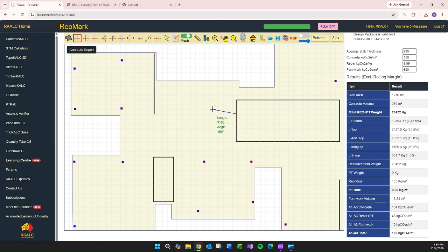Let's say I'm gonna draw here, activate polar because the building is rectangular. It will lock in the bar length by 12 meters, and then you draw the extent. So let's say you've got the extent from here all the way to there, and then you enter the rebar diameter, let's say 12 at 200, so it shows you the extent and how the bar is distributed.